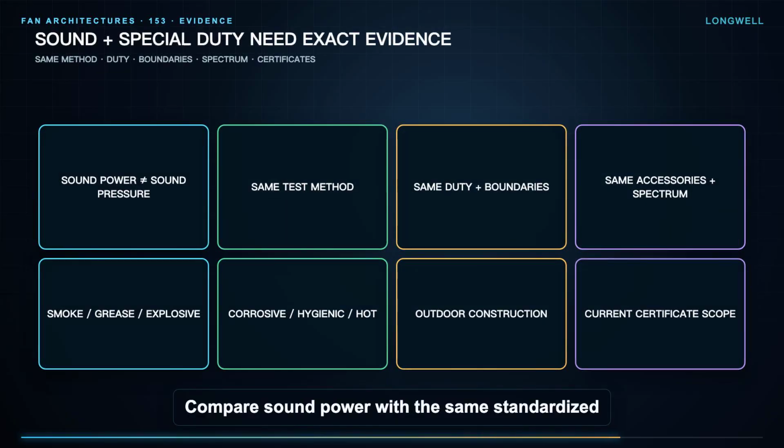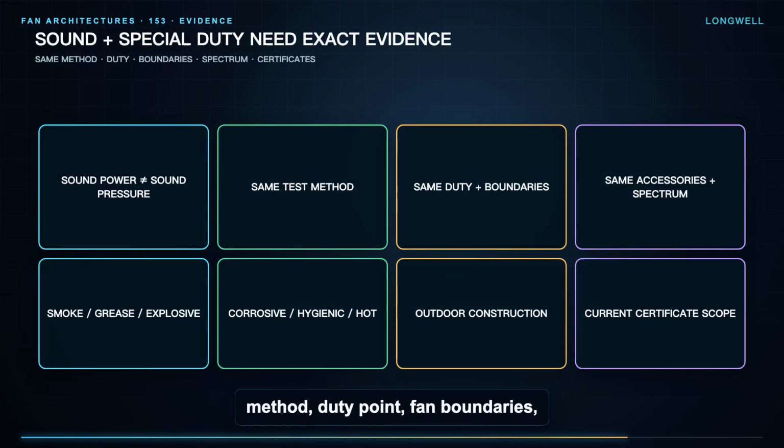Compare sound power with the same standardized method, duty point, fan boundaries, accessories, and frequency spectrum. Sound pressure in a room is a separate prediction. Smoke, grease, explosive, corrosive, hygienic, hot, or outdoor service requires exact construction and current certificates, not a family label.